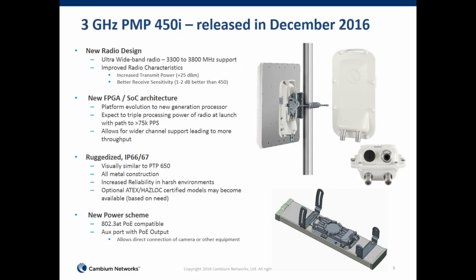It's a ruggedized enclosure, IP66/67. It's got the glands, as you can see there, and the connectorized version has the N-type connectors on the one on the right there. It's all metal construction, and we may introduce an ATEX Haz-Loc version of this should the need arise. There is a version of ATEX Haz-Loc certified in the 5 gigahertz radios, and if the need arises and there's requests for the 3 gig, we may pursue that as well.